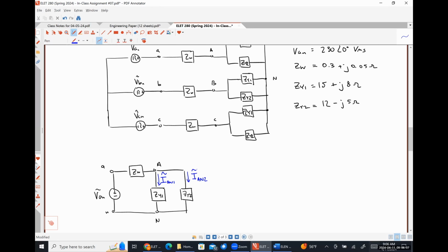So you're saying, Trilin, if I'm understanding you correctly, that if we were able to find the phase voltage across our loads, because our loads are in parallel, they're identical, we could divide that phase voltage by the impedance of each load, and that would give us our phase currents. I agree with that 100%. So how would we find that VAN? Same way last time I said we would do a parallel circuit now. Well, you could go current route, which is the equivalent plus zero.